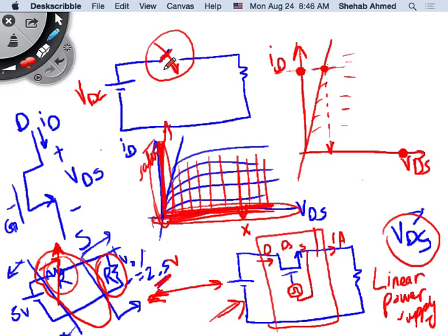The small value can have high currents. I can push the whole ID current that I want to push through. But because the value of resistance is small, I have a small voltage drop. Then the power losses are very small across this device. So if I'm able to operate in this fashion, right? This is a big if right now. If I'm able to do this, then I can satisfy my need to convert the voltages as well as minimize losses.